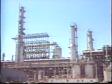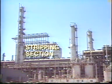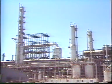The part of the column below the feed tray is called the stripping section. In the stripping section, light components not wanted in the bottom product are stripped or vaporized out of the liquid flowing down the column. The part of the tower above the feed tray is called the rectifying section. In the rectifying section, heavy materials not desired in the overhead product are condensed out of upward flowing vapors.